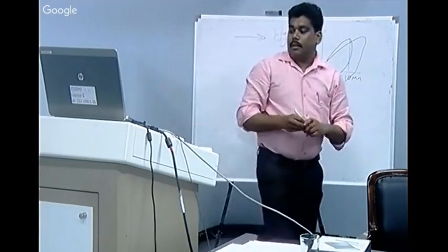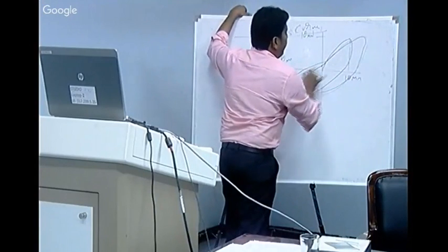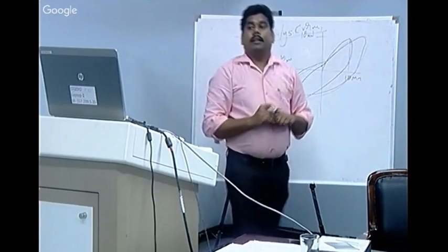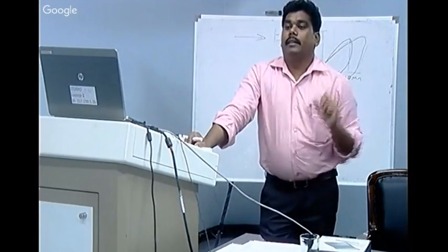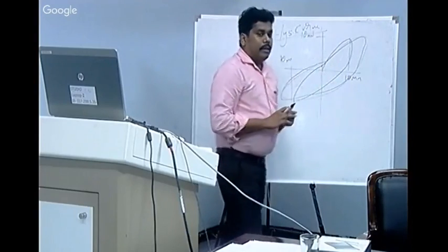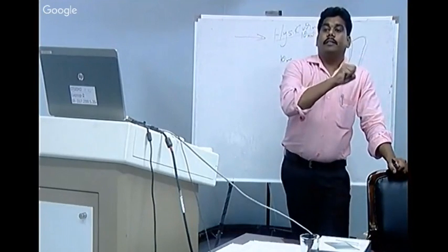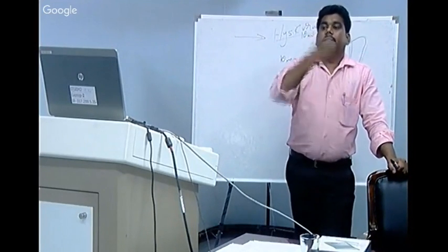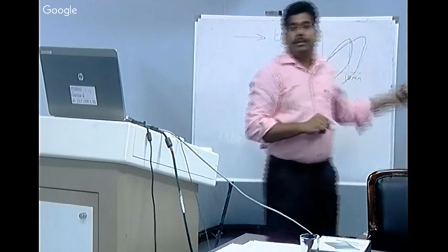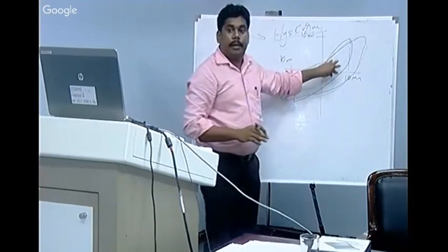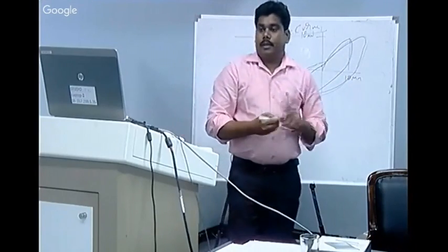What it explains is that the area enclosed in the curve is generally referred to as the energy dissipated during loading. The amount of energy dissipated means, during an earthquake, some amount of energy will be given to the structure in the form of earthquake force. The amount of energy will be absorbed by the building and dissipated. The amount of energy applied, absorbed, and dissipated can be understood from this. Here, this amount of energy is dissipated through the joint. It can be understood from the hysteresis loop.